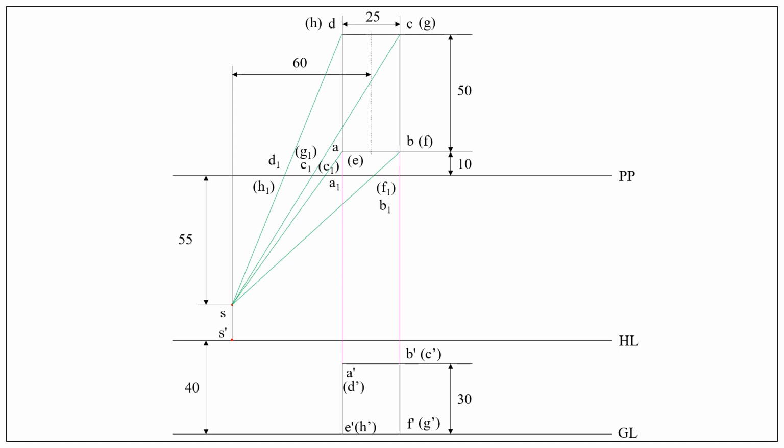Now connect all the corner points in the front view with station point S dash, that is front view of the station point S. So draw a line connecting S dash and A dash. Similarly, S dash and B dash, S dash E dash, S dash F dash.